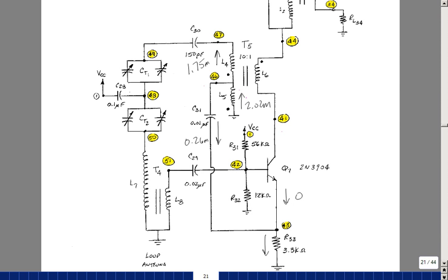Now, part of the reason for that is that with current going in this direction, it wants current to come out of the coil on this side, on the dotted side. And of course, current can't flow in that direction, so the transistor gets shut off. So what happened initially was we had current flowing in this direction. Some had gone back down in here, and that kind of held off the transistor. But because current was flowing in this direction, it wanted to pull current in here, and eventually did. The excess current came back up here, and eventually forced this current to now change directions. And then when that's happening, this is going to change directions and begin to decrease this current, which eventually will shut off the transistor. We're kind of back to where we started from.